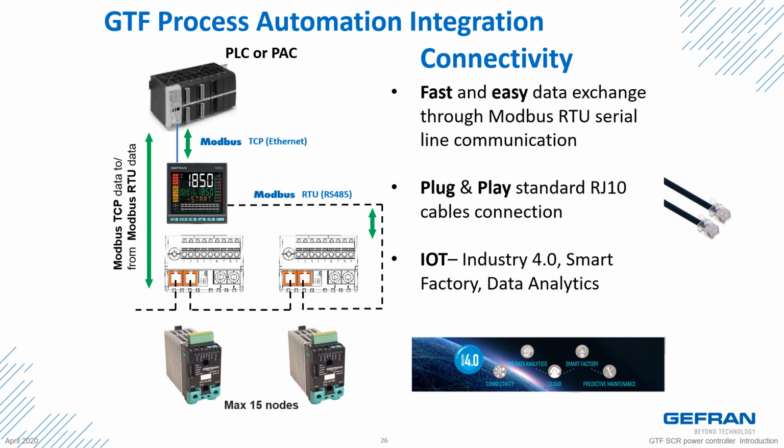The GTF power controller can interface with your programmable logic controller or programmable automation controller directly via Modbus RTU or through a gateway device via other protocols. Shown in this example is a Gefran 1850 controller that can be a Modbus RTU TCP bridge connecting up to 15 Modbus RTU devices.